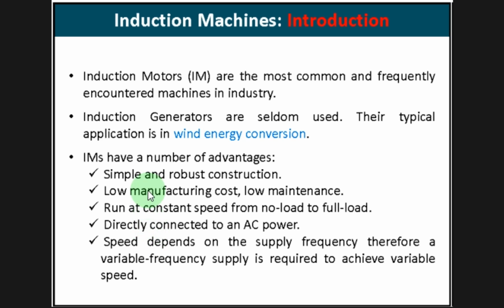Induction motors have a number of advantages. They are simple and robust in construction, low manufacturing cost, low maintenance, run at constant speed from no load to full load, not like DC machines, and they are directly connected to an AC power supply, and speed depends on the supply frequency. Therefore, if you want to change the speed, you have to change the frequency of the supply, right?